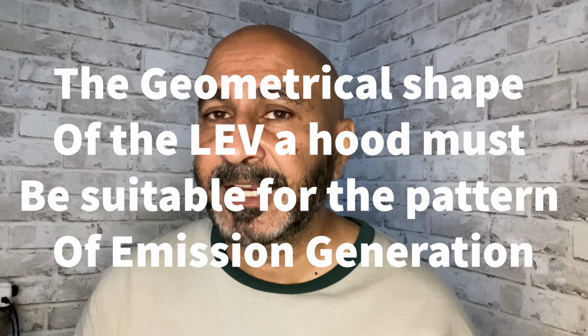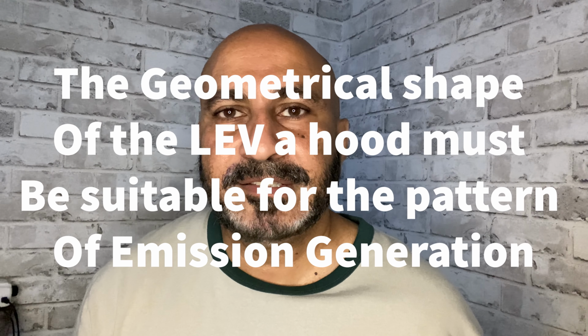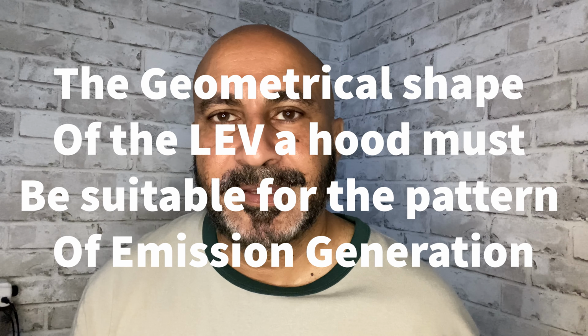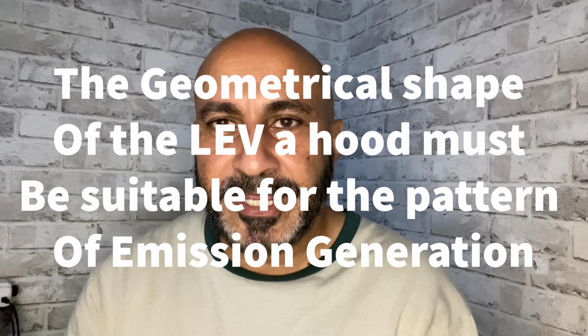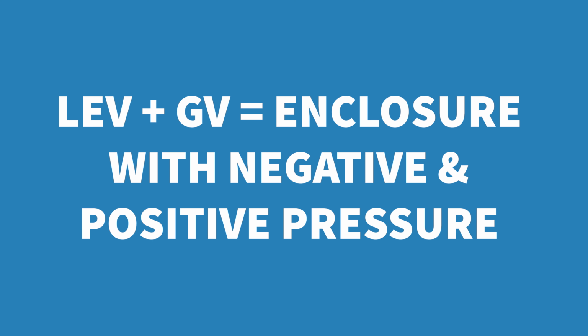So when I create a local exhaust ventilation system, what happens to the general ventilation design mechanism? It works. The whole negative and positive, the exhaust and the supply work together to create the overall pressurization of the room, and indirectly it will control the exfiltration and infiltration of air depending on how we work out the entire settings.